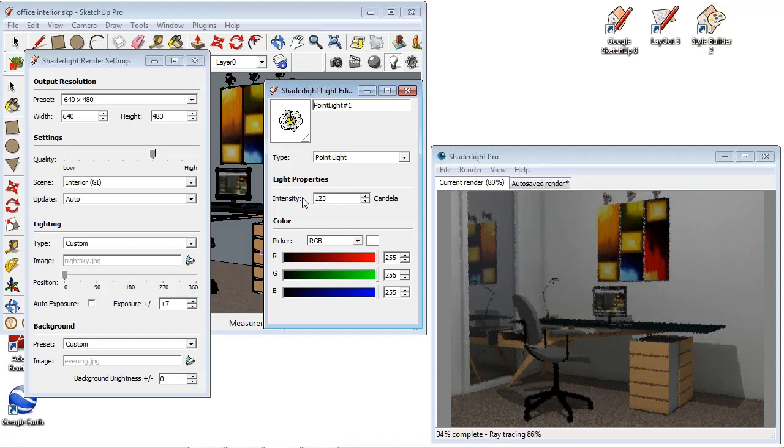If you have got a nighttime environment, an HDR environment, or perhaps even a blue sort of night sky environment, it will give your room that blue lighting. But to be honest, as soon as you put any lights inside your room, it kind of wipes out that effect. So it very much depends on what room you're going for. If you're going for a room that you really want to show up that's lit perhaps by a nighttime sort of moon, then yes, you will need that. But in this particular scene, because I'm putting lights into it, no, we don't need to use those.